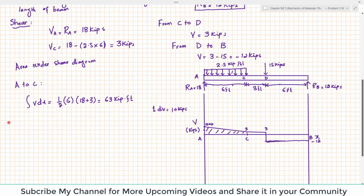Now from C to D, you can see this is a rectangle. So this length is 3 and this height is 3. So again, the integral of V dx will be equal to 3 multiplied by 3, and this area will be equal to 9 kips into feet. From D to B, again the area under the shear force diagram,